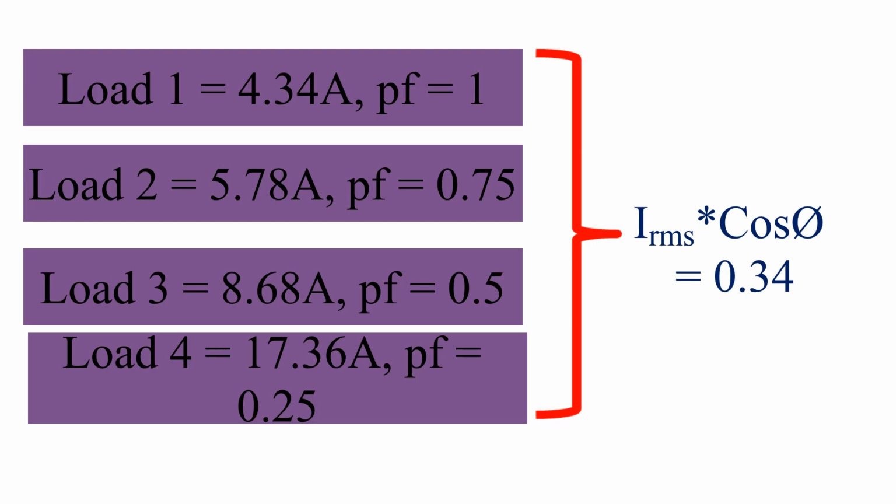See the currents of load 2, 3 and 4. All these exceed the maximum permissible value of current. So when we connect these loads at the inverter output, it will result in the failure of IGBTs, burn the connection wires and filter inductors, etc.